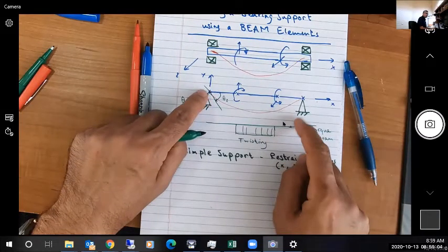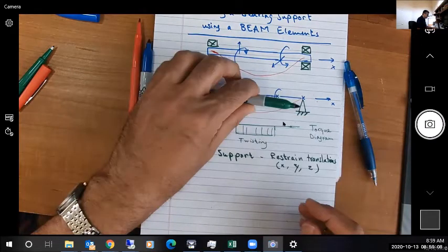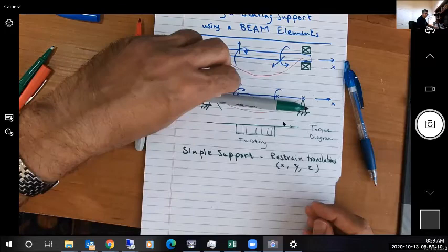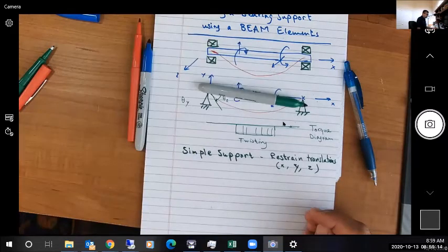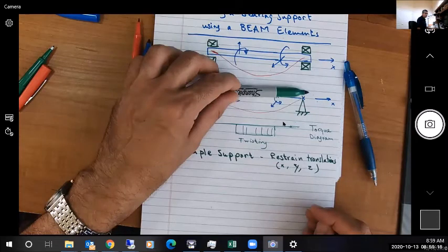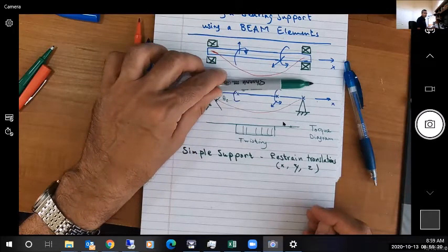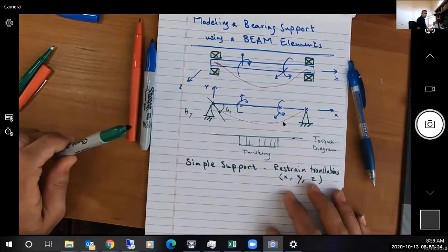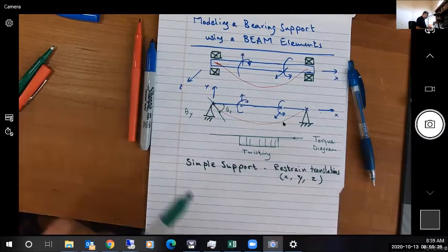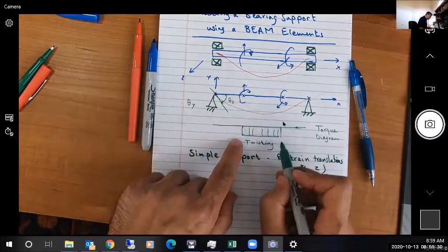It's also holding it in place in the Y direction, so it's not allowing the shaft to rotate about the Z axis. But because both of them are along the X axis, the shaft can spin, which would not allow us numerically to run a static structure analysis. And that's why we say we are gonna add something away from this area.